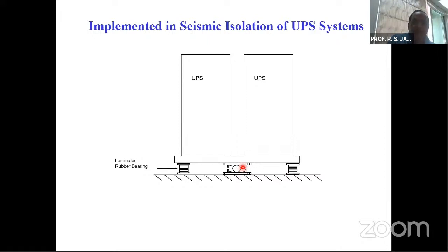And the purpose of this sliding bearing was to take primarily the majority of the vertical load of this one, and the load transferred to these bearings was tried to be reduced. And because of this, one can ensure the stability of the isolation system.